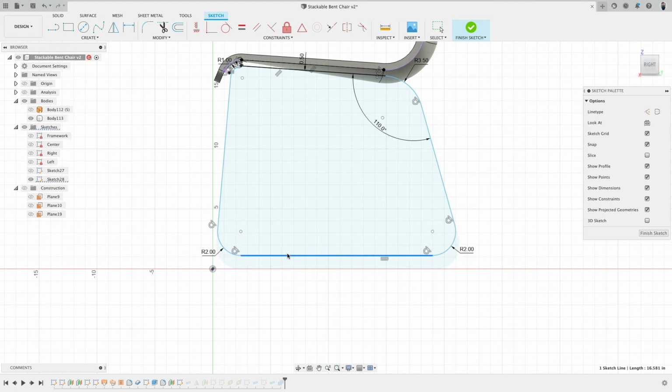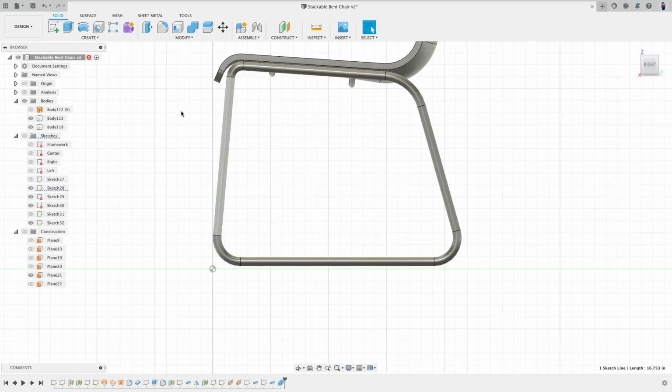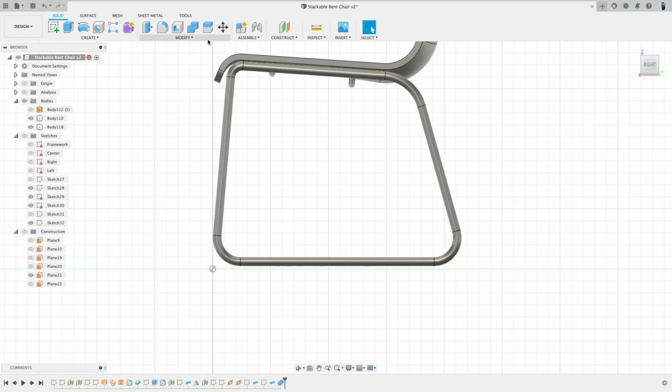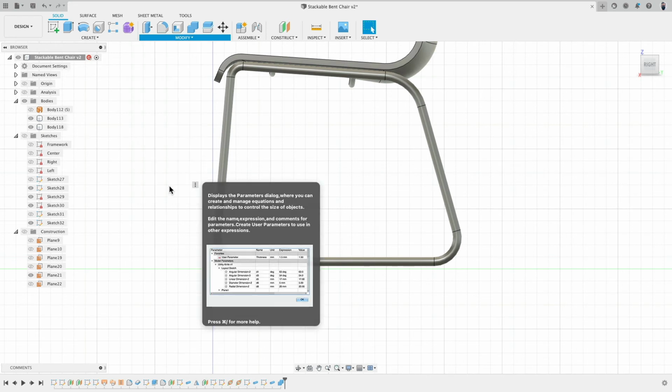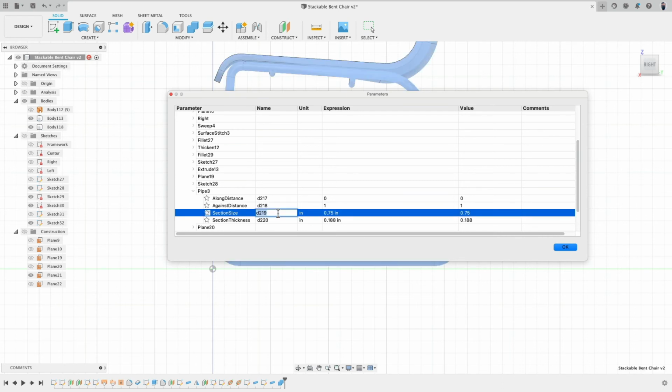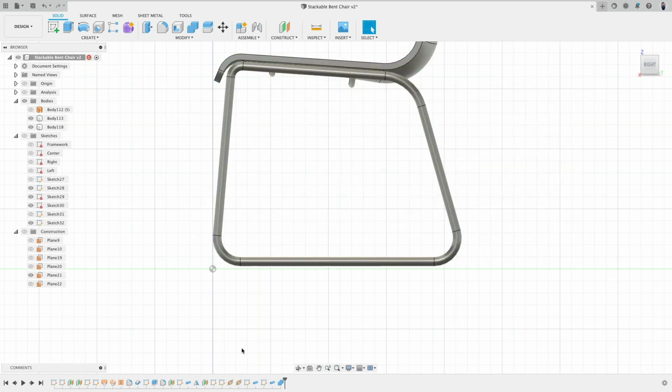This whole thing has to be 0.25 off the ground because I think that is what the pipe is. Oh, this is actually another really nice example of how we could use this. So this is D219, but this is way too complicated. So let's go to change parameter and then we're 219. So here we can call this pipe main, copy, very good.